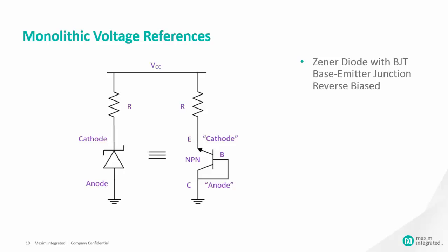Zener diodes can be fabricated easily in a planar process, where all active junctions are on the silicon surface, which is easy and inexpensive, but such devices suffer from external contaminations and crystal dislocations that are all contributors to voltage instabilities. A solution to the problem is the buried Zener, in which the Zener junctions are created far, that is, several micrometers, below the silicon surface. This way, a very accurate, low noise and low temperature coefficient reference can be achieved.